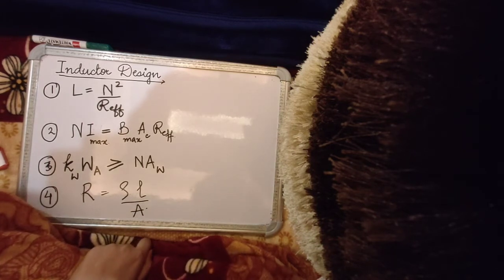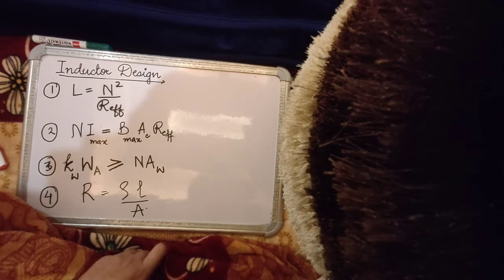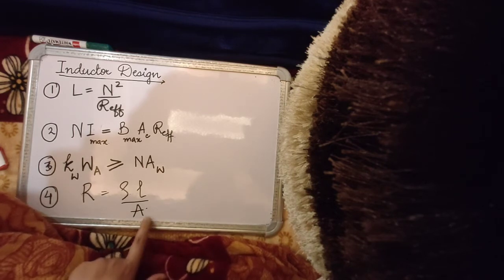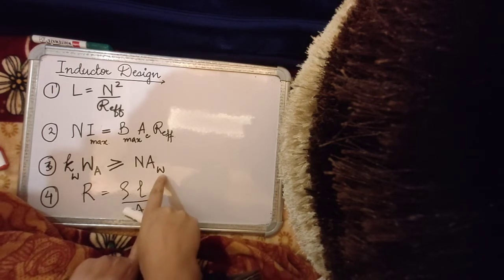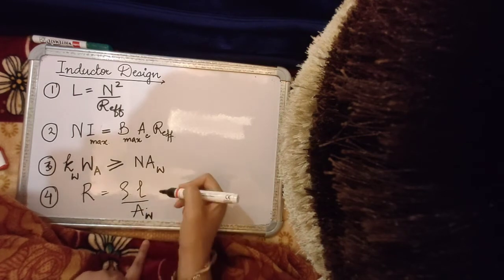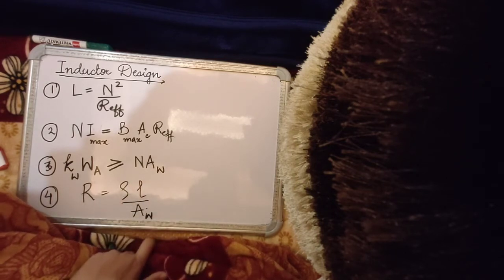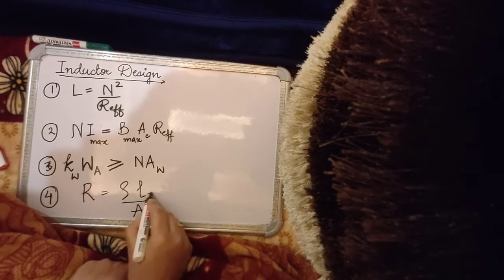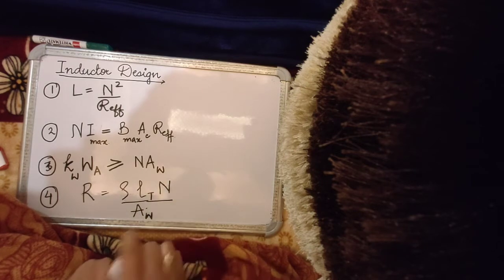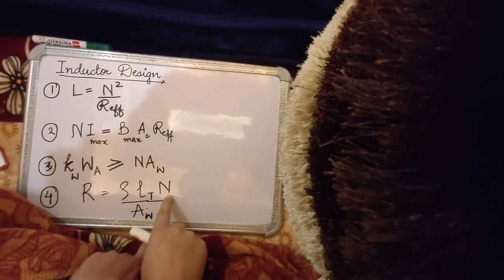Right? Now what is this L and what is this A? Till now the L that we were discussing in the last class was related to reluctance, that was the length that was traversed within the core by the flux. This length is the length of the wire which we are winding over the core, and this area is the area of cross section of the winding, which is the same as AW. So I hope you do not confuse yourself between various areas. This is the area of cross section of the core. This is the area of cross section of the winding or the wire, which is used here as well as here. And this length over here is the total length of the wire that we are winding over the core. If the wire has n number of turns and the length per turn is given, then I can simply use this, where LT is length per turn, and multiply it by the number of turns to get the total length, right?